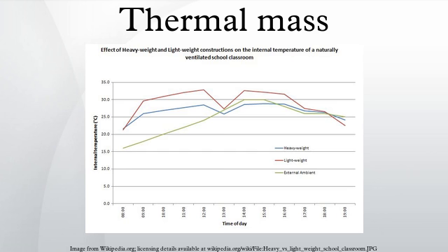As an extensive property, heat capacity is characteristic of an object. Its corresponding intensive property is specific heat capacity, expressed in terms of a measure of the amount of material such as mass or number of moles, which must be multiplied by similar units to give the heat capacity of the entire body of material. Thus the heat capacity can be equivalently calculated as the product of the mass m of the body and the specific heat capacity c for the material, or the product of the number of moles of molecules present n and the molar specific heat capacity.